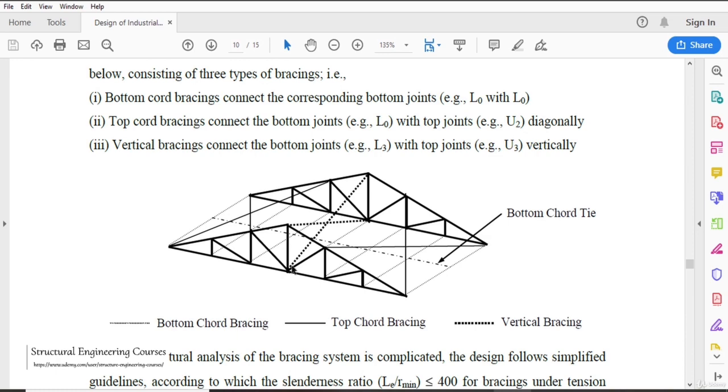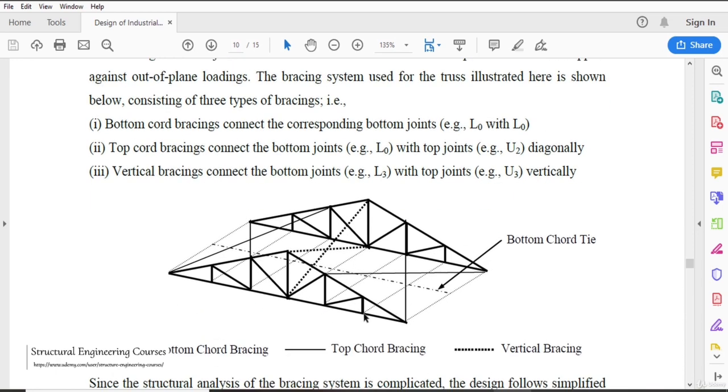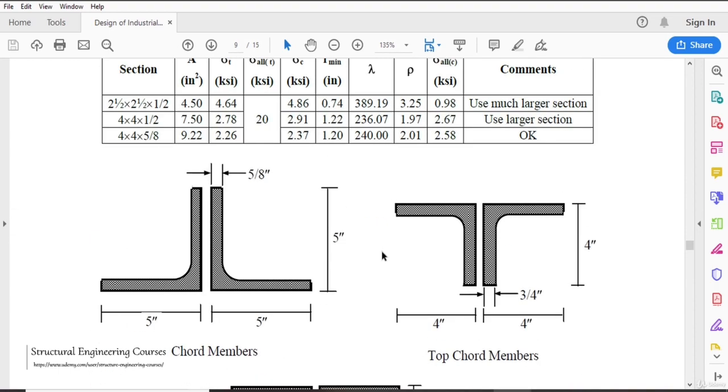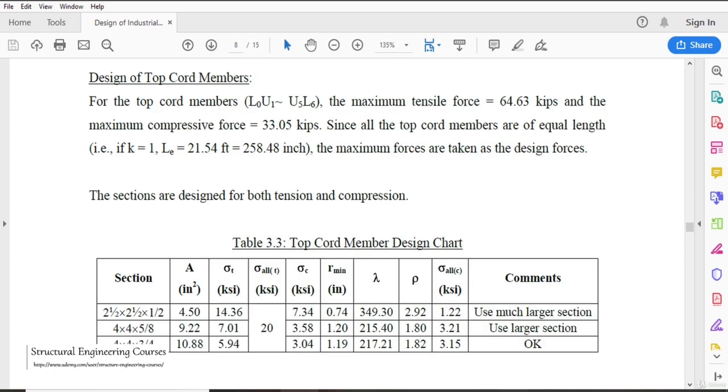After that we can join all the bottom chords. So that is why we have not taken any LY in the truss sections here. If we are not providing any of these members, that is 1, 2, 3, 4 and 5 members, then in that case we do need to provide LY from this point to this point. And all the members and all the ties we are joining, in addition bracings we are also joining. So in that case we don't really need to assign the LY.